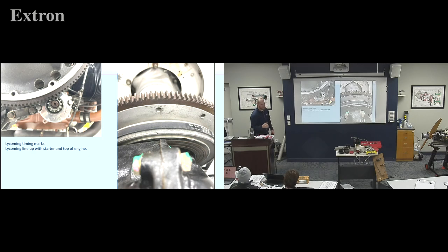I love them because the push rods for the valves are on top of the engine. There's 3 things that are all on top. The push rods for the valves are on top of the engine. When you time a Lycoming, the timing mark on the back of it is lined up with the top of the engine case. And Lycoming, because they're the top dog engines, that number 1 cylinder, it ain't afraid of the prop.